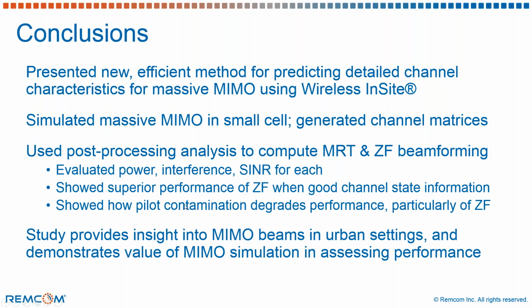In this particular case, zero forcing was much superior when there was good channel state information, but when we introduced pilot contamination, it had a severe effect on that performance.